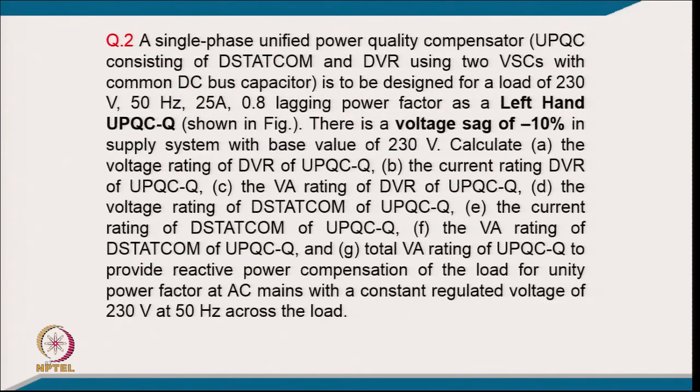So, coming to numerical example second: a single phase UPQC consisting of D STATCOM and DVR using 2 VSC with a common DC bus capacitor is designed for a load of 230 volt, 50 hertz, 25 ampere, 0.8 lagging power factor at the load end of the UPQC, and there is a voltage sag of 10% in the supply system with the base supply voltage of 230 volt.